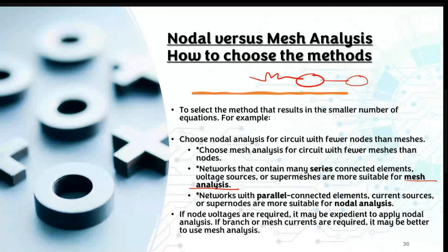But for parallel-connected elements, which create a node, it's more suitable to choose nodal analysis. If node voltages are required, it may be expedient to apply nodal analysis. If branch or mesh currents are required, it's better to choose the mesh analysis method.